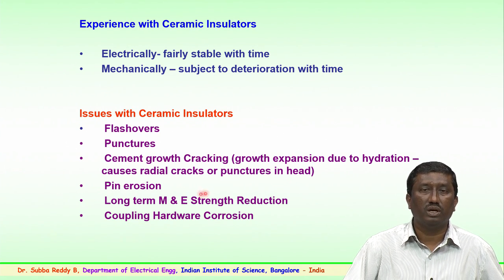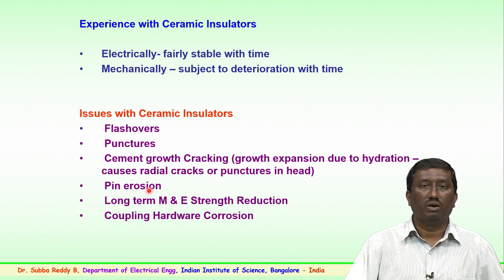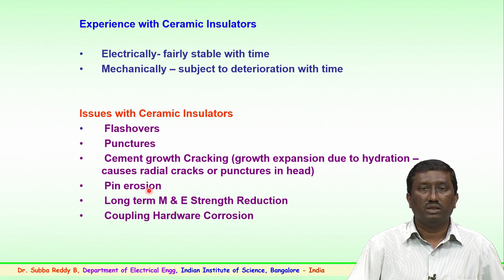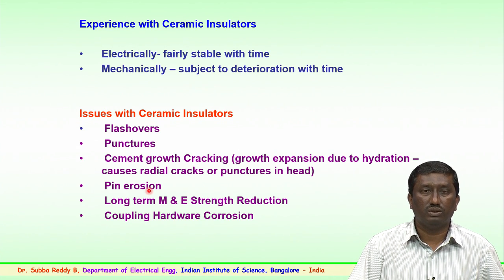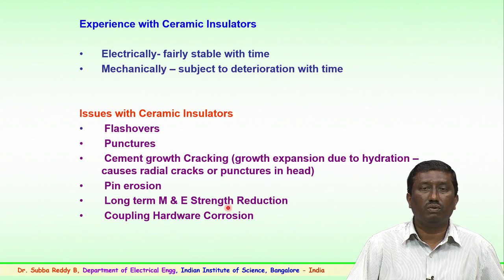Then pin corrosion. Again, depending upon the climate or environmental factors, over a period of time corrosion on the pin has been noticed. This could also lead to the failure of insulators or issues with the ceramic insulators. Then long term mechanical and electrical strength reduction takes place because of these issues.